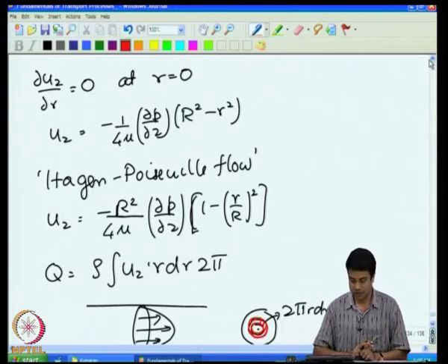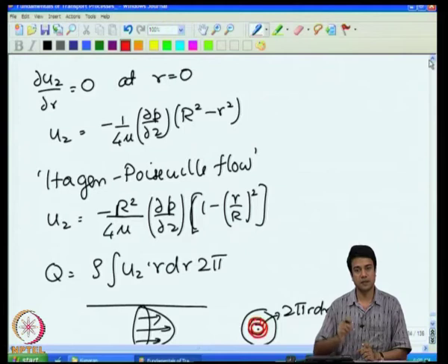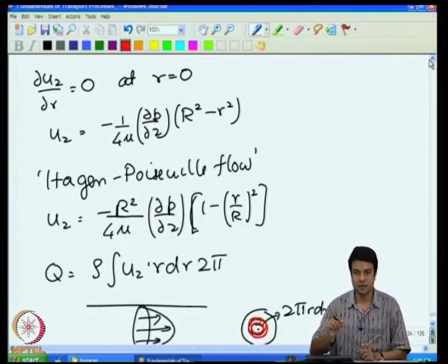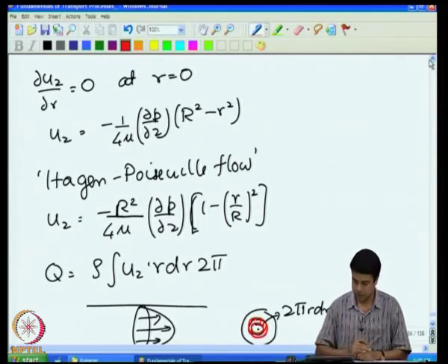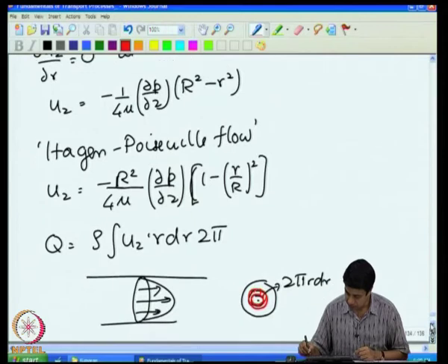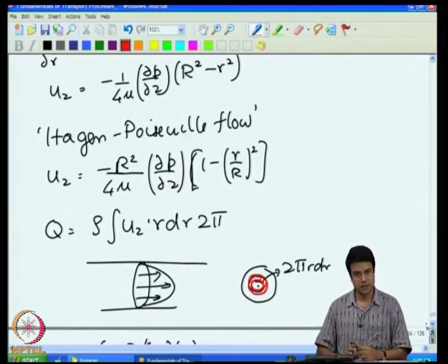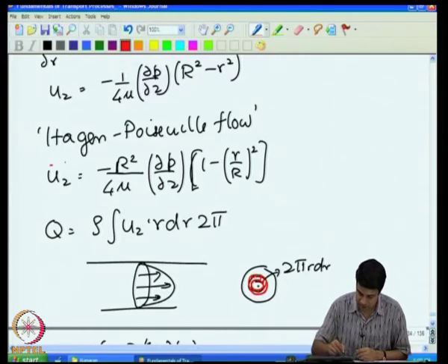So, therefore, I have to do an integral over each strip of the area of the velocity within that strip times the area of that strip, integrated from 0 to the wall of the pipe. Each strip of the area in this case is a strip between r and r plus dr. The velocity within that strip is u z of r, which is basically given here.